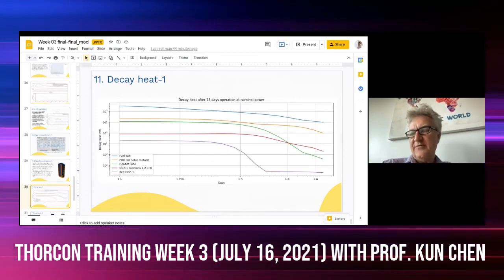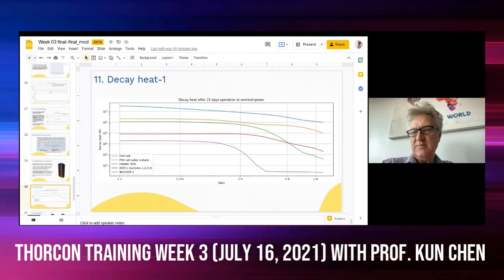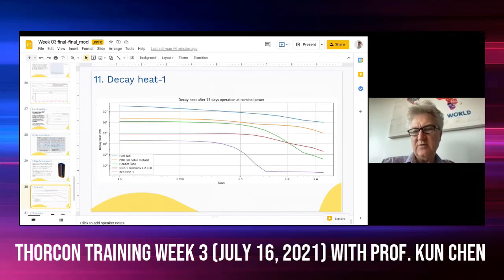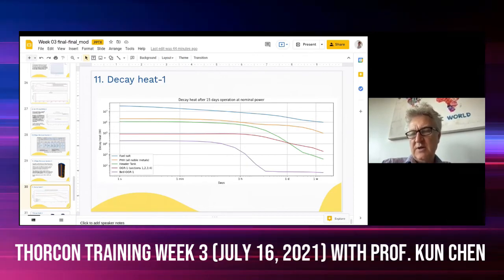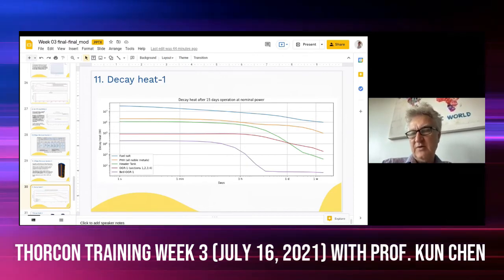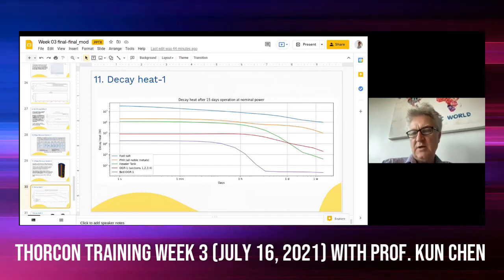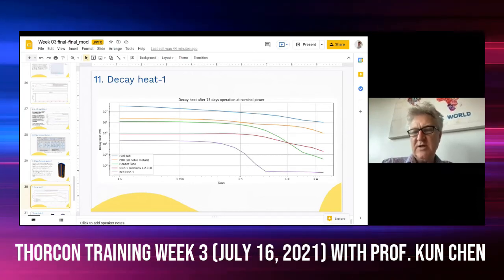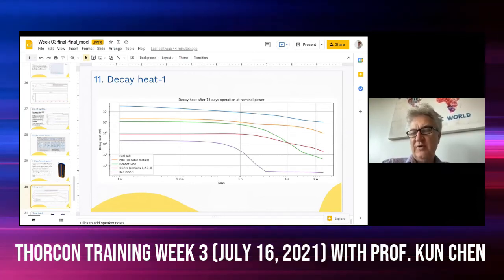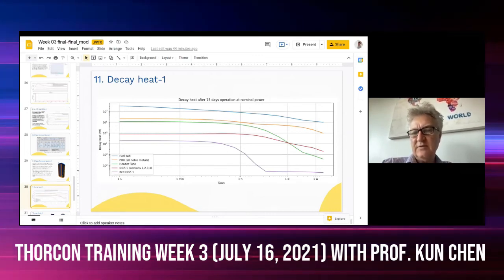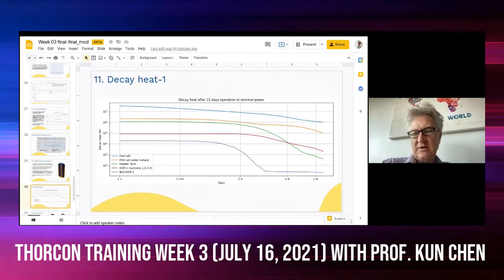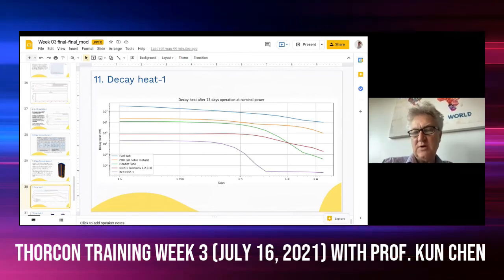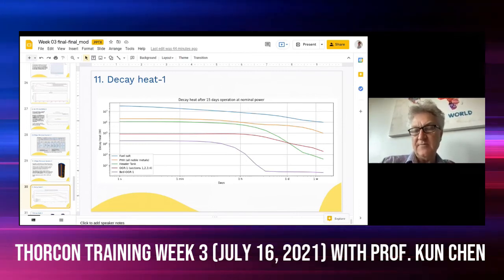We have avoided having seams between pieces of graphite in the center of the core because that could lead to salt that's trapped in the seam. And then you would get a concentrated heat source without the coolant flowing by it. If the salt fissions, we want it to keep flowing because that's where 90% of the heat is going.